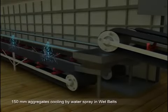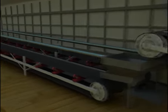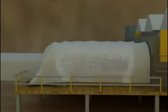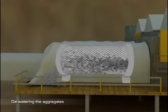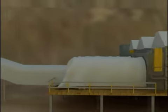To allow the extended time of travel for the aggregates in the wet belt, the conveyors move at a much lower speed. The temperature inside the wet belts is maintained at 4 degrees centigrade. Water from the cooled aggregates is removed by passing it through the dewatering rotating screen at the other end of the wet belt.